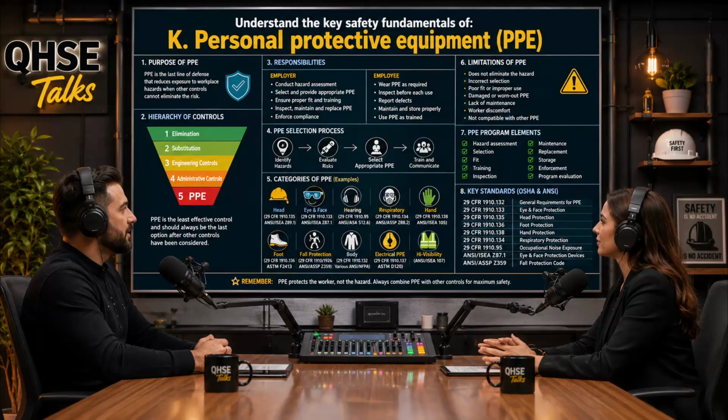First, welding operations. When outfitting a welder, the protective clothing must be constructed from natural fibers like heavy cotton or wool or leather, right? Yes. Why? Because if a welder wears a high-performance, moisture-wicking synthetic shirt made of polyester or nylon and a 2,000-degree piece of slag lands on their chest, the fabric doesn't just catch fire, does it? No, it's so much worse.